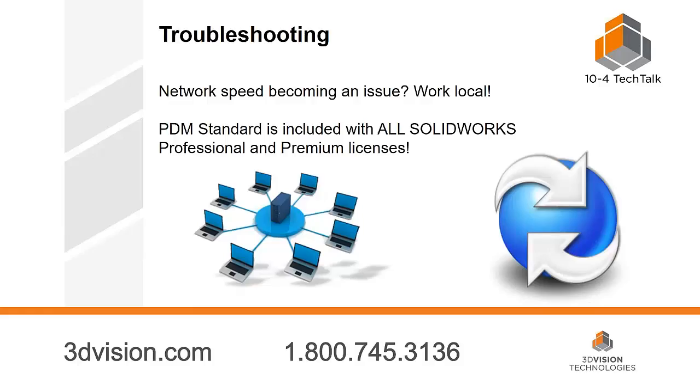So if you notice, network speed was one of those that goes across all three of those categories. Network speeds are something that we see all the time that causes an issue. Your connection to a server and transferring that can slow down the process of opening or saving. What we recommend is actually looking at PDM Standard, which you might already own if you have SOLIDWORKS Professional or Premium. So if you have Professional or Premium, definitely look at what PDM can do for you right now.